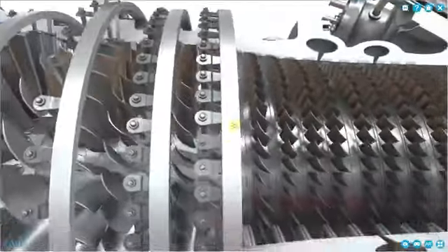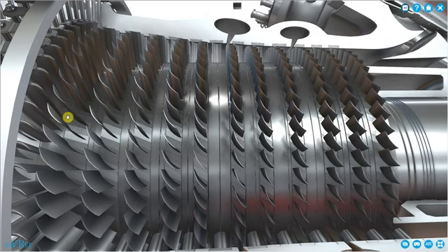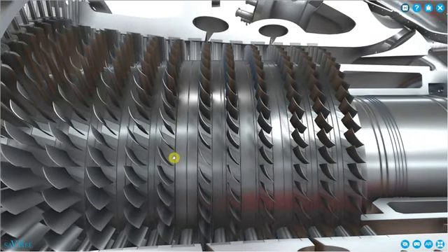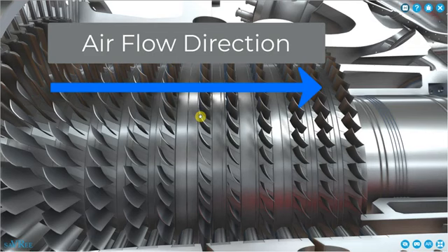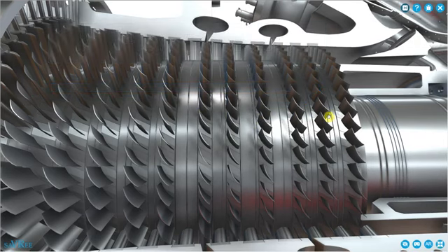We draw the air in. It flows past a series of compressor blades, and we're going to increase the pressure as the air moves across each of these blades. And remember that each row of blades is called a stage. So at every stage, as we move from left to right, we're going to increase the air pressure and correspondingly the temperature as well.